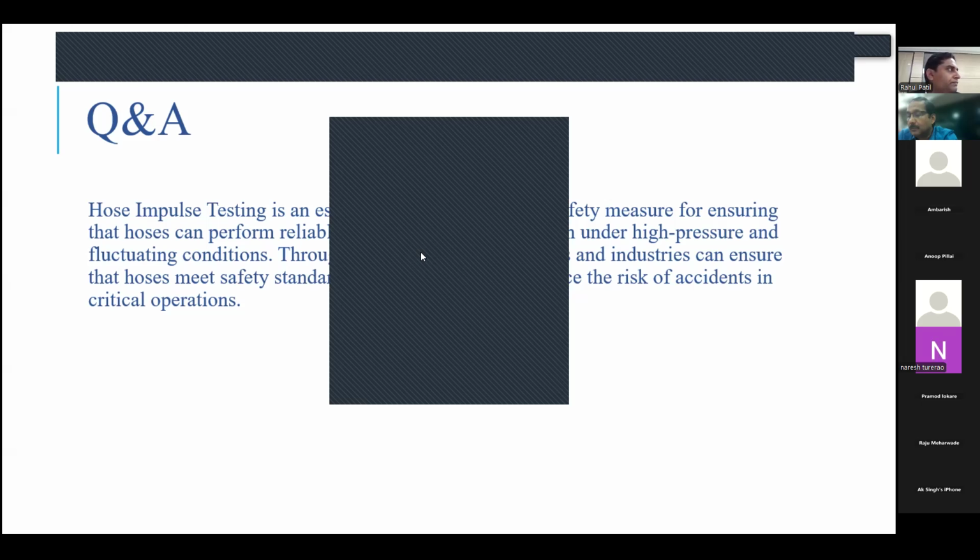Yes, sir. ISO 10380 is meant for SS corrugated flexible hoses. It does not call for the impulse test, but some customers, like aerospace customers, OEM customers and IATF customers, are asking for impulse testing as a specific requirement for metallic hoses. Not everything is standard driven. Certain OEMs or system integrators define their own criteria, and we can do that testing as well.